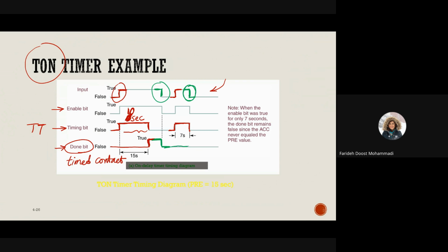So here, I don't get the chance to go to 1 because the delay was not completed. I was waiting for 7 seconds. I had to reach 10 seconds in order to go to 1. But before reaching 1, I received another command, another action saying that you need to go back to 0.